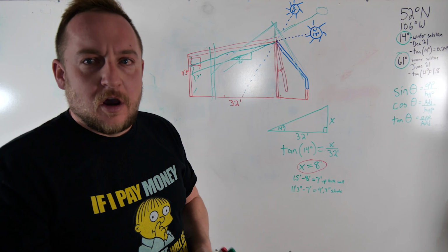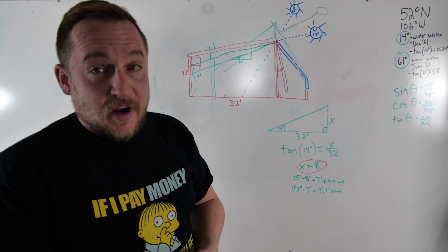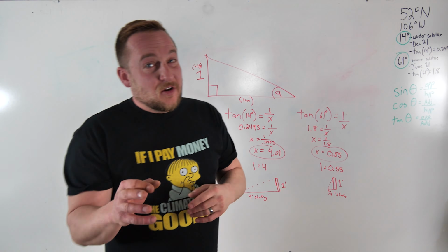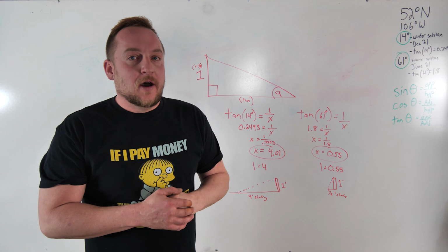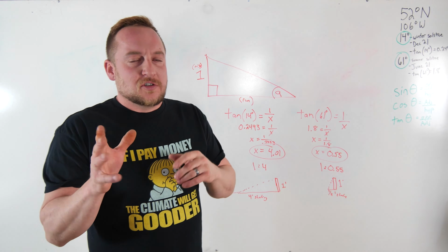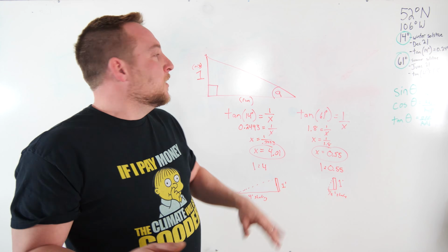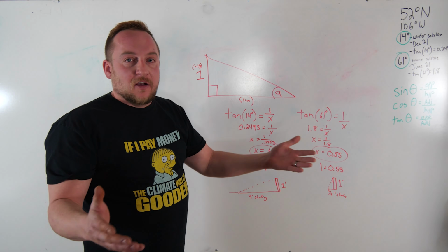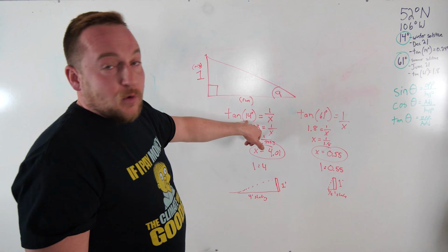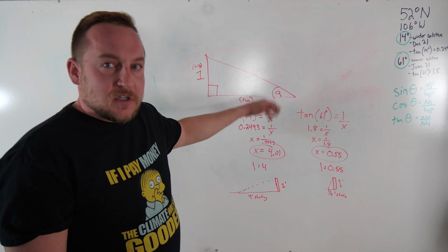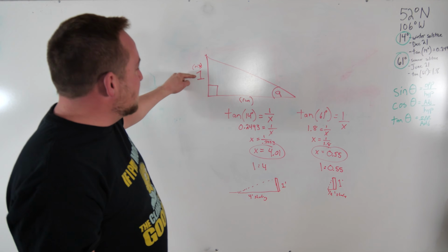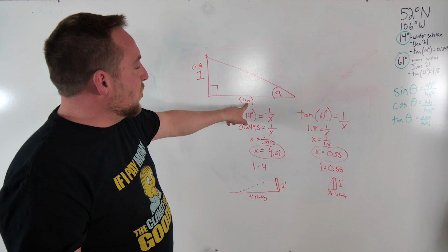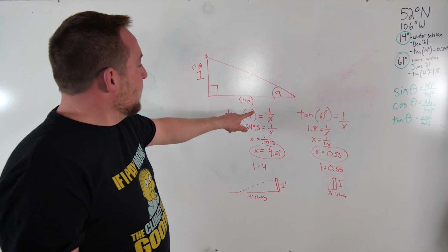It all comes down to trigonometric functions, cosine, tan, right angle triangles. You can literally figure out anything you want to with the sun angles. This is another really easy way to do quick calculations so you can kind of guess and check on whatever project you're doing. But we're essentially looking for rise over run at the angles that we need. So tan 14, that's my winter solstice when the sun is lowest, and do a rise of just 1. So I'm looking for a ratio. So just type 1 in the calculation, and we're looking for the adjacent side.